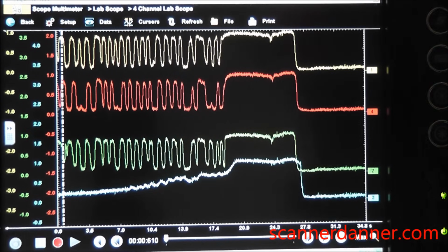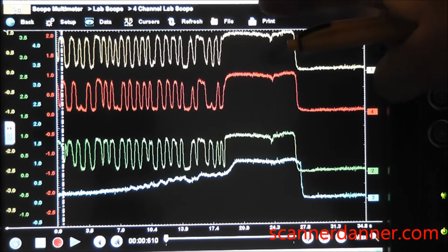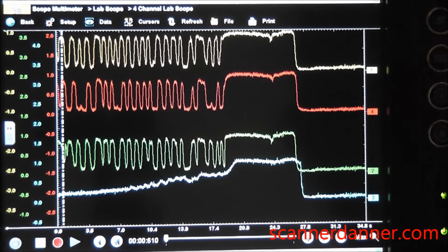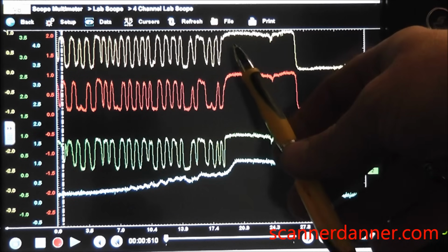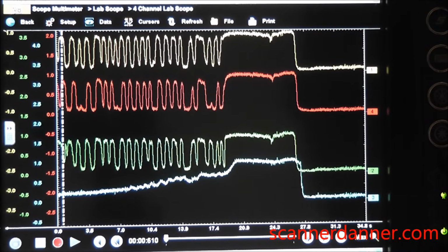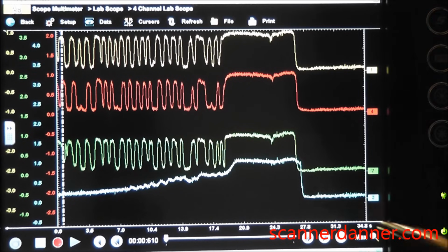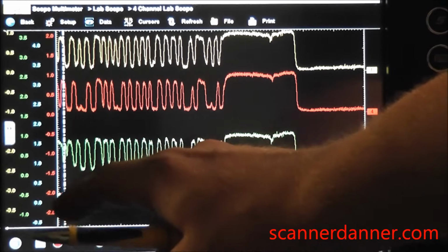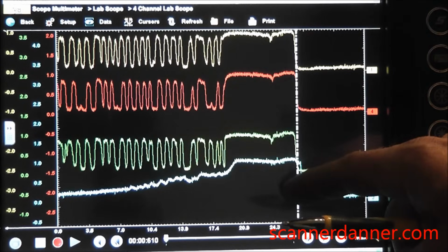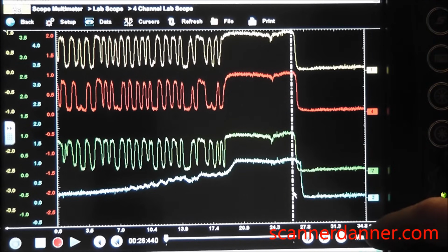And in this area here is where I'm adding fuel, and you see all the O2s went rich. At that moment in time, the short-term fuel trim command takes all the fuel away, and so I keep it there for a while. And the reason I add that propane for a period of time is I want to give that short-term value a chance to take away a lot of fuel, not just a little bit. So I let it go for a while, and then I shut the propane off here. And what I can do is zoom in on this area now, where everything drops lean right there.